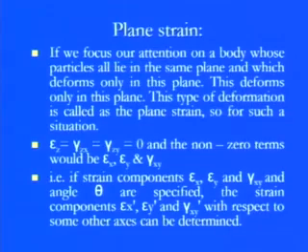So now you see, the last part of this lecture is the plane strain, because as we know that the plane stress is playing a key role in the formation of the stresses, then what about the plane strain? If we focus our attention on a body whose particles are all lying in the same plane, meaning there is no change in the plane, they are exactly well set up within the plane, and which deform only in the plane, then we do not have to go for all the other parts of the deformation and analyze those things in a complicated way. So this deformation in only one plane is called the plane strain, and this situation is very generalized.